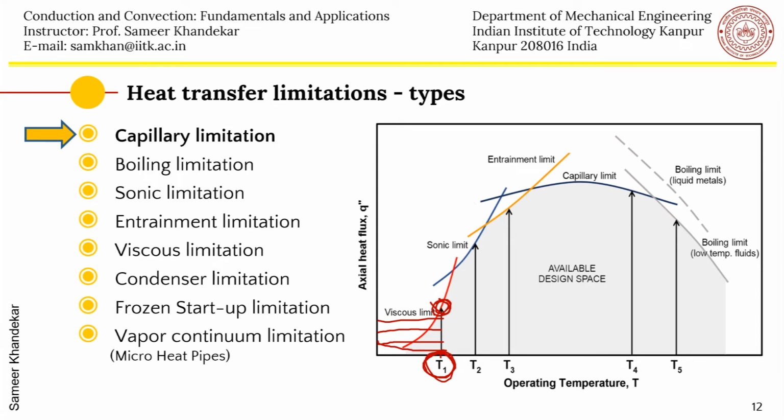So as you keep on increasing the heat power and you allow the heat pipe to come to steady state operation, by adjusting the condensing temperature so that the adiabatic temperature is maintained at a temperature of T1, let us say. And then slowly you will see that after a while the thermal resistance suddenly shoots up and you have a limitation. That means now the heat pipe has practically stopped working, and whatever small thermal resistance was there, now it is so big that you are very sure that this liquid-vapor internal circulation has actually stopped. Okay. So this is what will happen.